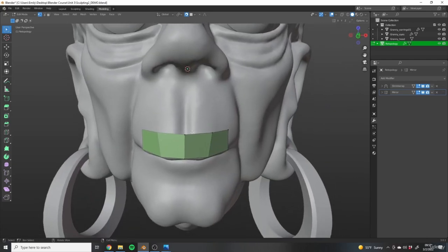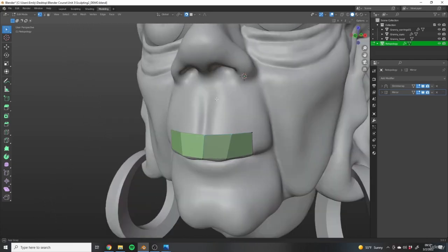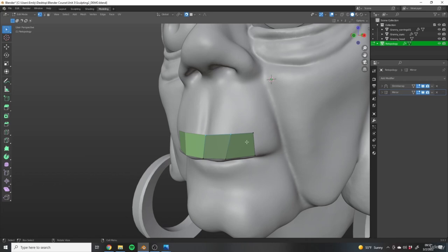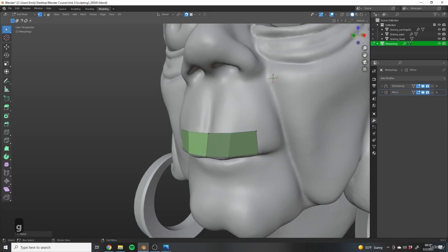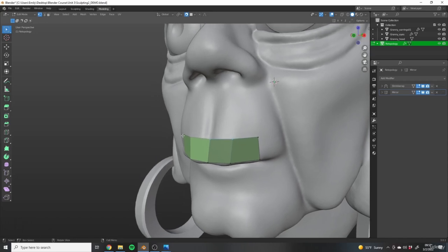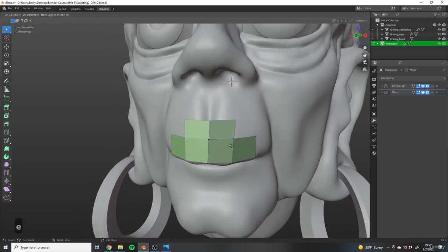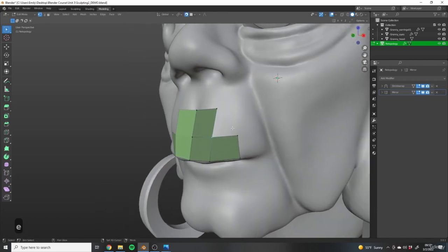So what this does is it is basically extended functionality for the fill tool, which we used in our modeling section. We would press F and we would fill in certain quads, lines, and faces. So what the F2 does, let's extrude this up so I can show you. Normally, without the F2 add-on, if we pressed F with this point selected, it would draw a triangle right here.